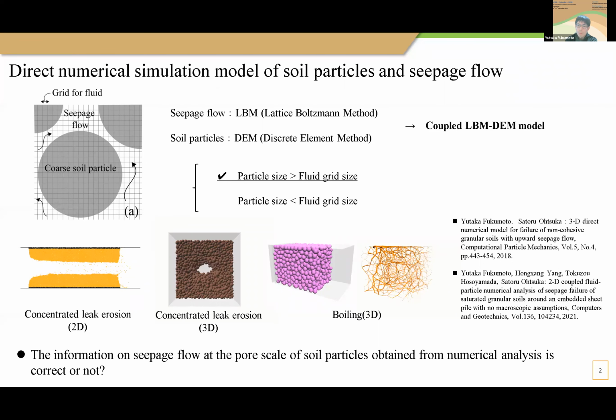For seepage flow, we employ the lattice-Boltzmann method, LBM, and for soil particles, we employ the DEM, discrete element method. These methods are combined, and we are investigating a coupled LBM-DEM model. What you see here are examples of our applications. These are concentrated leak erosion in 2D and 3D, and seepage failure problems such as boiling in 3D.